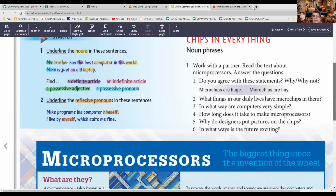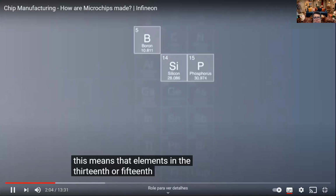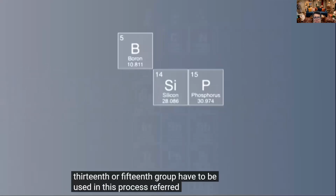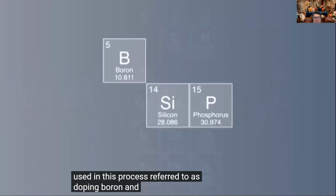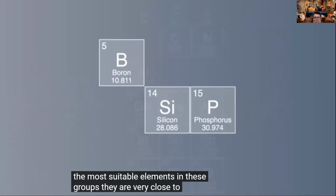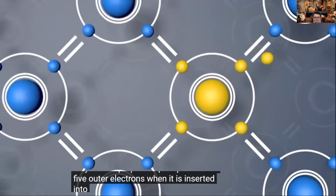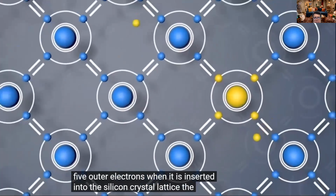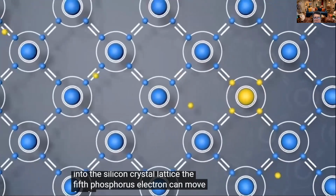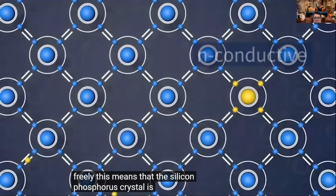This means that elements in the 13th or 15th group have to be used in this process, referred to as doping. Boron and phosphorus atoms are the most suitable elements in these groups. They are very close to silicon on the periodic table and therefore have very similar properties. Phosphorus has 5 outer electrons. When it is inserted into the silicon crystal lattice, the 5th phosphorus electron can move freely. This means that the silicon phosphorus crystal is N-conductive.